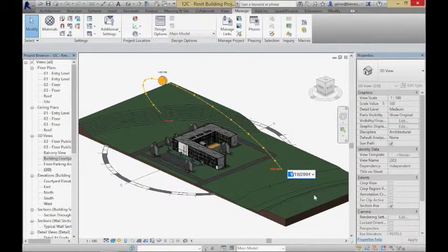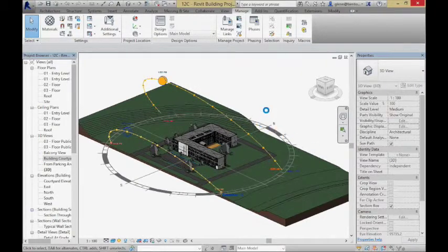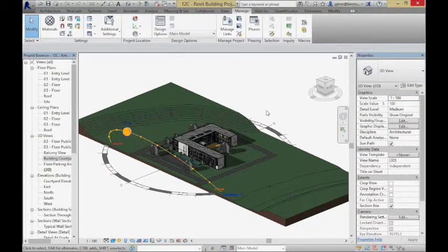If I change that instead to be like 12:10, as we're coming up right now, you'll see the sun stays much lower in the sky, and it actually casts much longer shadows. Okay, so depending upon what time of year, you get very different shadow behaviors. And we actually use this in passive solar design to think about how to orient the building, how to take advantage of the sun when we want it, which is typically in the colder times of the year, and how to shade ourselves from the sun in the warmer times of the year when we don't want to gather the heat from the sun.